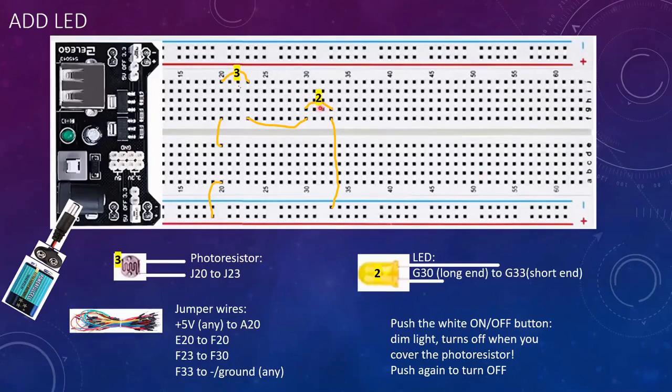And of course, to get this to work really well, you'd have to tune the exact amount of resistance in this to the type of LED you're using. This is just kind of a demonstration, so we'll see kind of a dimly lit LED turning on and off when we stick a hand over the photoresistor. Let me just get the other camera back on.